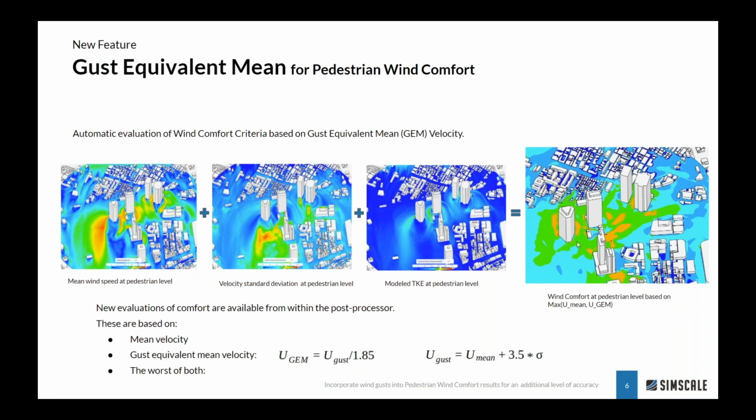And the picture on the right side presents the overall yearly or seasonal wind comfort criterion. So there we basically take all the directions that we have computed and combine them with the weather statistics. So there you don't see usually much directionality with the results, but more a combination of the prevailing wind directions and also obviously the local architecture and the massings of the building.